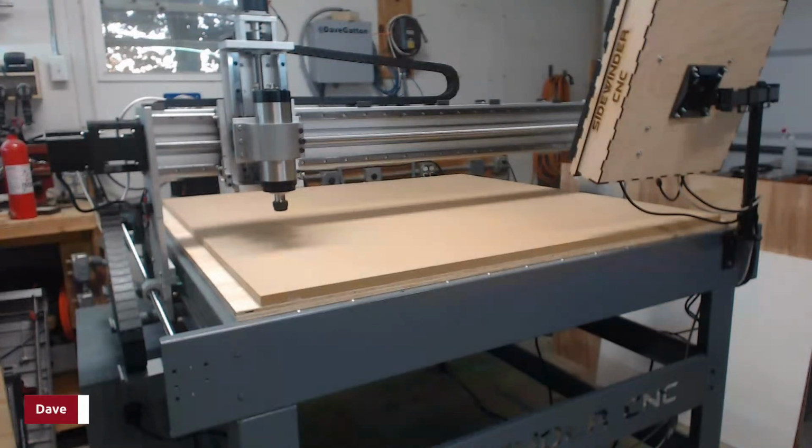It's a good thing I have a manual mill, because they made the plates up there where the NEMA 23 motor sets really high. You couldn't fit the coupler that they included, and it's even a 40 millimeter long coupler. It would not even reach. They had that so high. I don't know whether they did that on purpose or what, but anyway, you need to take that apart, take them two side plates off, and I took like 6 millimeters off of each one of them to get that to work. But that is what I've got so far.